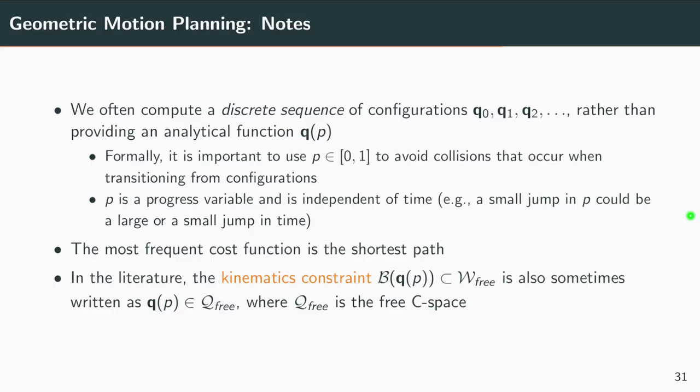One example could be this curtain over here, right? If I plan a motion from this side to the other side of the curtain, and I have a sample point here and a sample point on the other side, and then I check that all the samples are collision free, then that will be true, but I will have to go through the curtain and I will hit the obstacle. That's why it's very difficult to correctly define it just with discrete samples, unless these samples are much closer than the smallest size of the obstacle, right? But in practice, that's still what we often do.